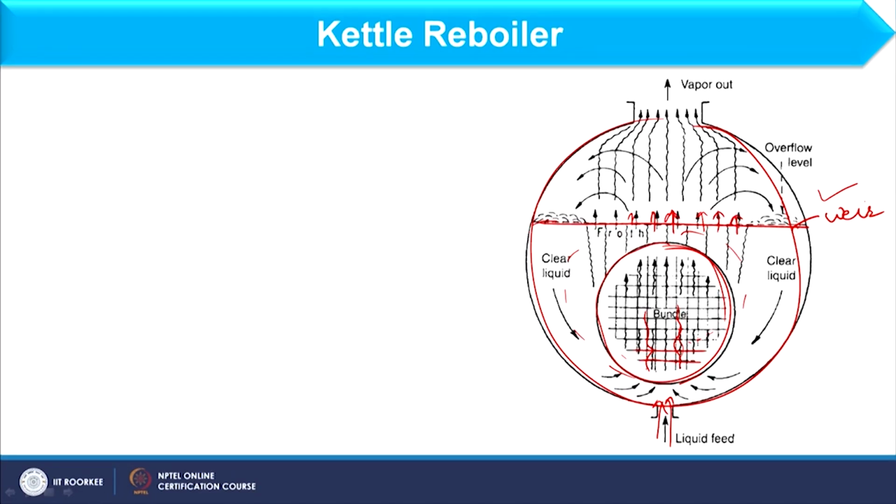And therefore, at this location of the reboiler, we continuously have froth as well as foam, right. So, after vapor-liquid separation, this froth separates, and whatever foam is there, that also separates, and the vapor completely moves upward like this, right, and the liquid goes to the other side of the weir and exits from that side as the final product, right.